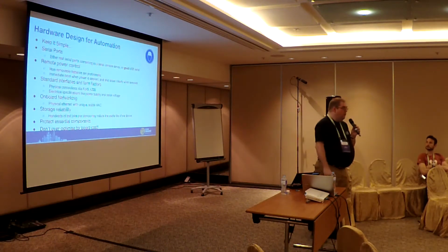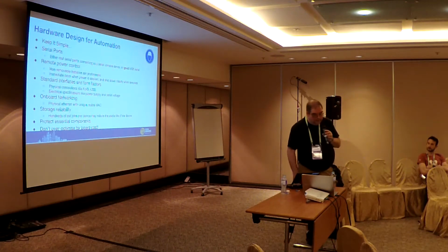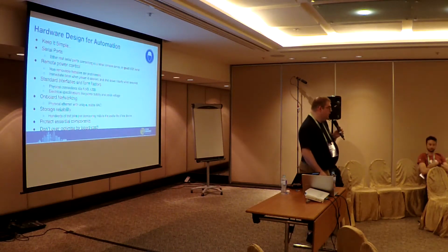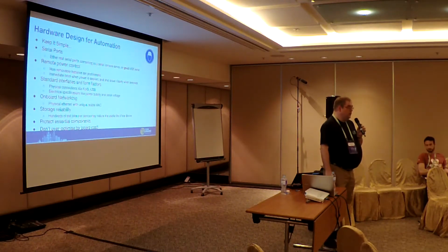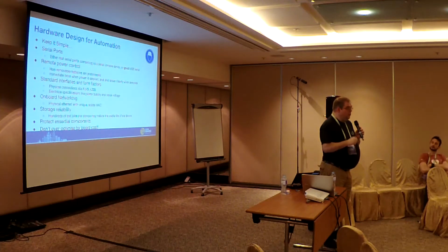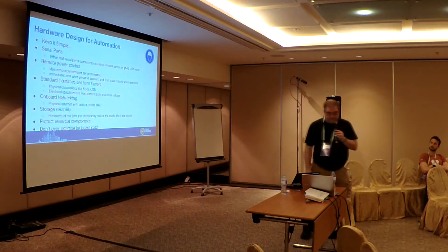Standard interfaces and form factors are a good plan. Please use normal physical connections. Use RJ45, use USB. Don't need a custom connection to get one of those. Don't make us need adapters, because those are the things that will be fragile. Those are the things that will get lost. Those are the things that make your board harder to work with.